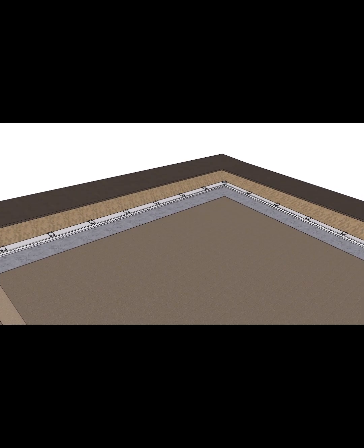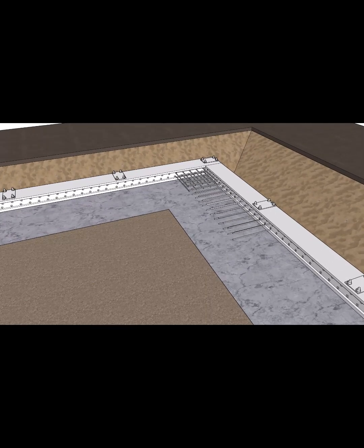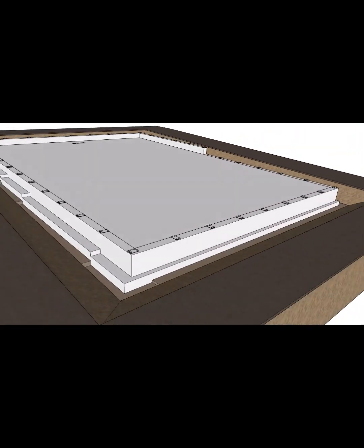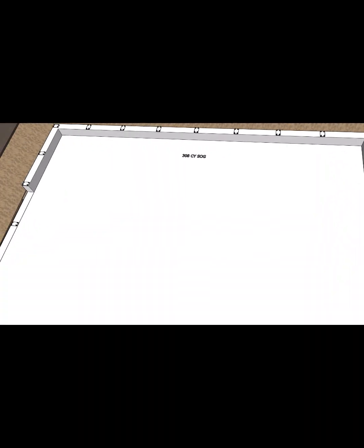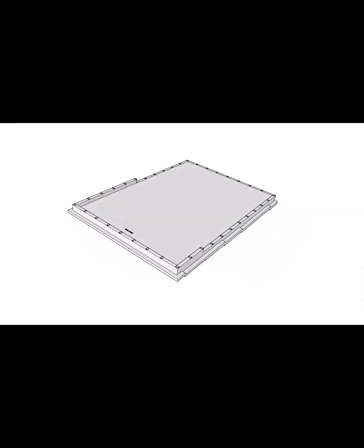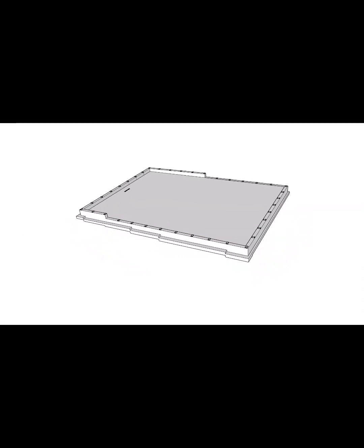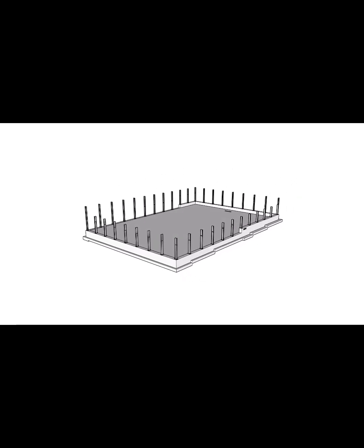Rod busters will install the form saver dowels and the double mats of rebar in the slab on grade. Lamb places and finishes the slab on grade. Wet curing blankets will be needed. Once the concrete has cured and the columns are installed, then Lamb's final task is to install the grout beds under each column.